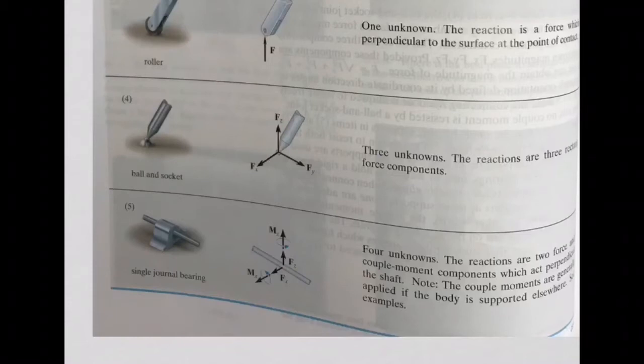So it means a reaction Fz. So Z is this vertical axis here, right? So a reaction Fz will appear. If you try to move this crankshaft in the X direction, that will not be possible as well. So then you will have a reaction Fx. Okay? If you want to move the crankshaft in this Y direction, that will be allowed. So it means no reaction in that direction.